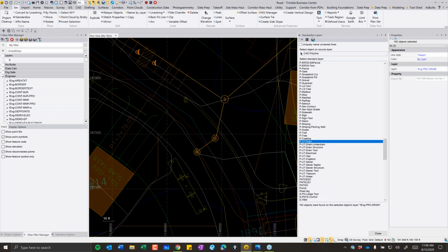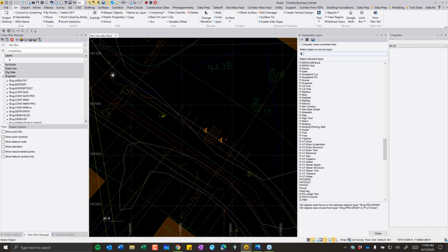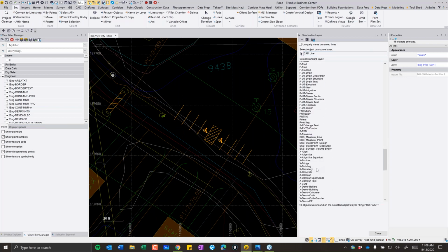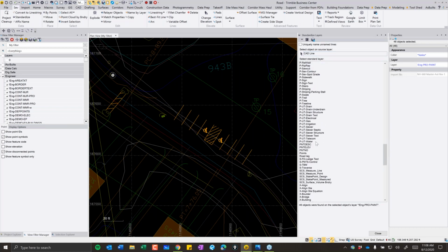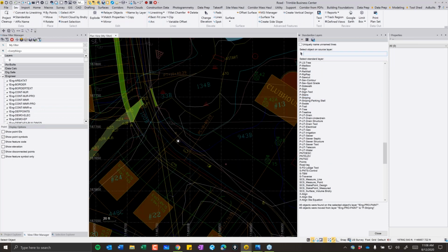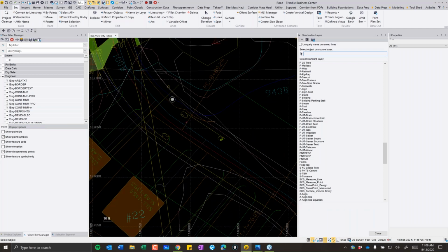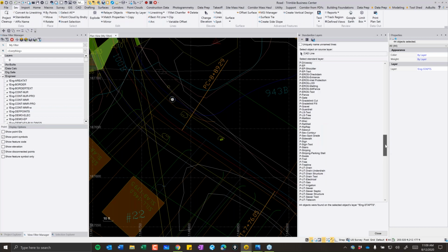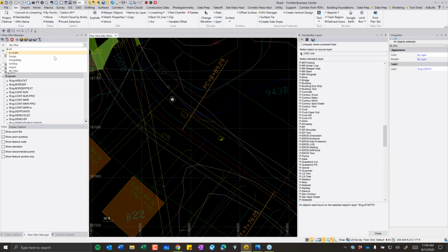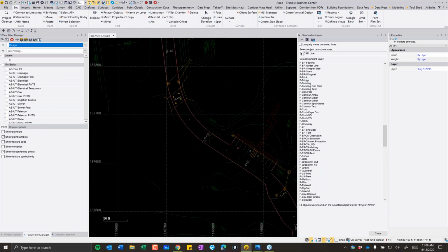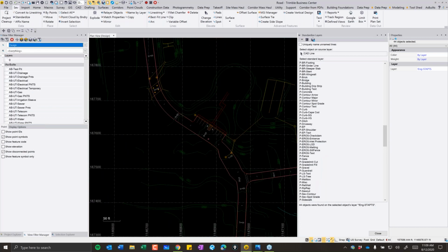Okay, so in this process, you're basically taking the CAD layers from the engineer and you're putting them onto the layers and grouping the data as you want it for your work process. Is that kind of what you're doing here? Exactly, because I've already spent the time in creating my layer groups based upon how I send it out to the field, how I'm going to use the data. So by using the standardize tool, it's a very quick process to get everything sorted out. So when I toggle my view filter and I go to my design, that's all my data that I'm actually going to use to compile this model. So that makes it very useful.